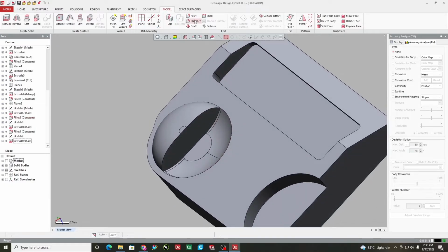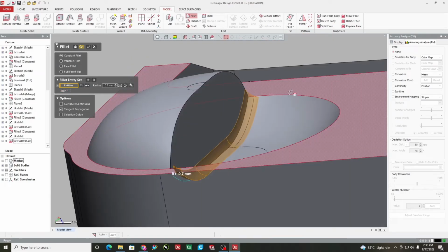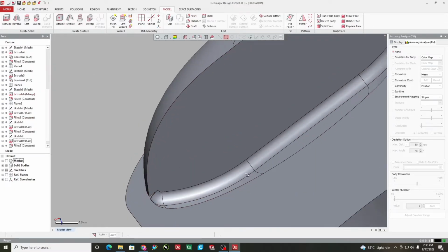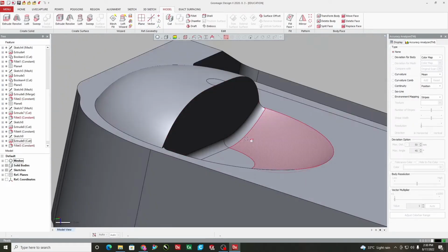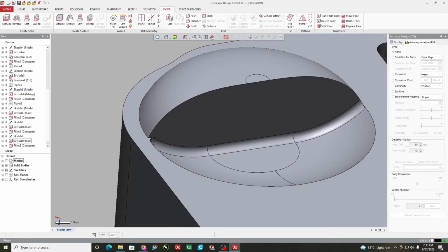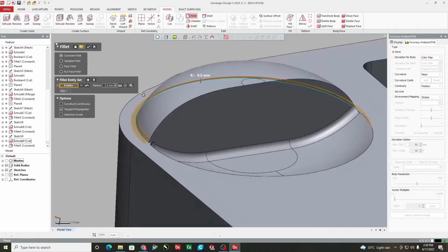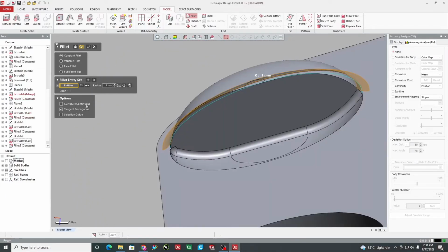Now, we are generating fillets down there. Small fillets which are observed from the mesh, a 0.7 mm fillet is being given here. Now, the fillet is made 1 mm here or 0.5 mm. Only small approximations are being taken, then we will match it with the obtained mesh. This fillet is also to be given on the edge at the back of the dome. Again, this is given as 1 mm.